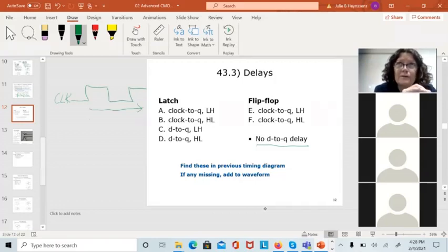And the capacitance is dominated by the number of gates, the gate oxide capacitance. So if I put 10 inverters off of this output, the delay may be like here. And this is called a fan out of 10. And I will talk about fan out in lab 2. It's going to have a much higher delay than if I only put one gate on the output.